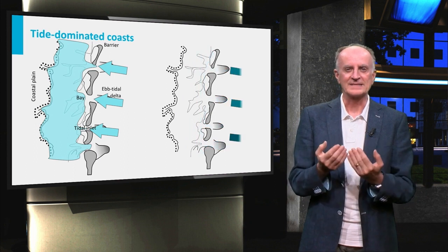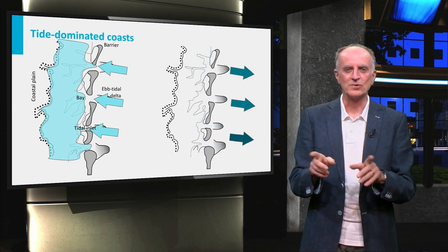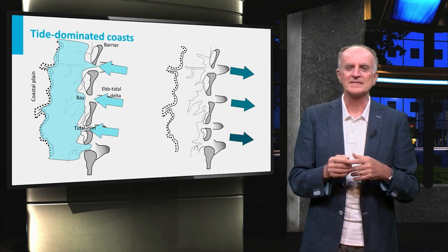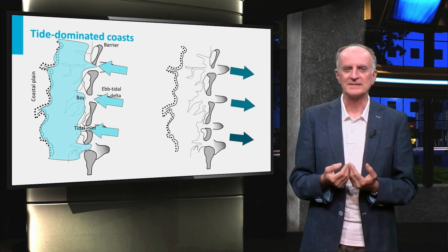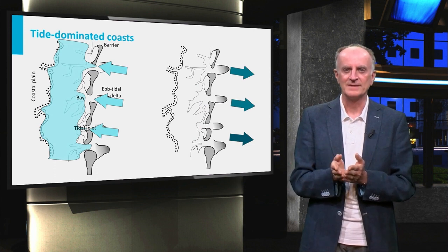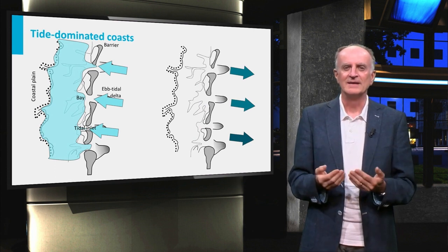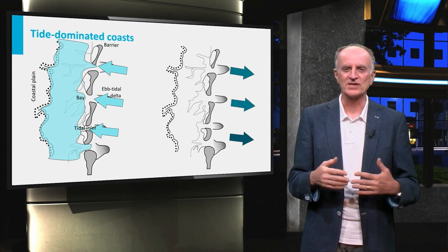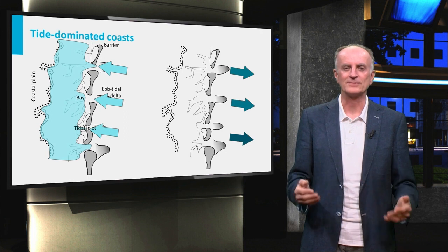When peak tide passes and sea level decreases, waters will retreat towards the sea. They will do this not in the same homogeneous way they did while rising, but rather getting concentrated in narrow flow paths. Because of the narrower paths, velocity will increase and tides become erosive, forming a network of channels and bringing sediments back to the sea.